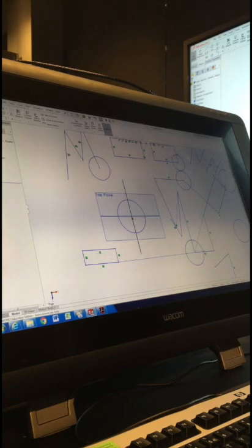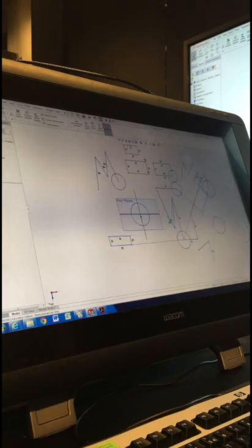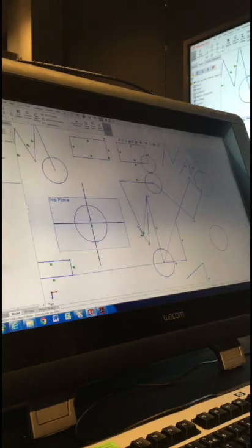Now, the other thing I want to talk about in this sketch is the use of the origin. When I'm sketching or working on any parts, I typically hide my planes because it can make it difficult to see the origin and see other features. So at the moment, where you can see my 3 planes over here, it's very hard to see that center point. So I'm just going to click on those planes in the feature tree on the left and press hide. So I'm going to hide each of those planes.